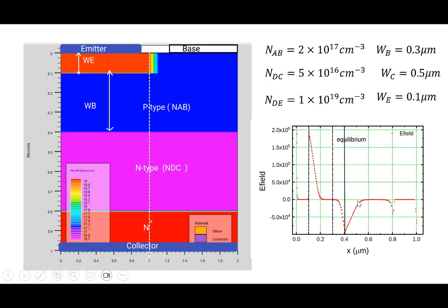So this is the other junction here. And note that little bit of space charge region, I won't call it a depletion region. A more general name is space charge region. Wherever you see charges because of movement of electrons and so on, it's a space charge region. So this is a space charge region here, there's another space charge region here, and then there is a little bit here also. Why? Because the doping here is 5 times 10 to the 16.